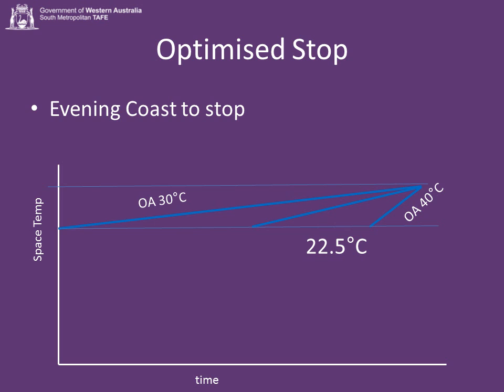What we can do is look at the outside air temperature, look at the inside air temperature, and say, oh look, the building warms up at 10 degrees an hour. If we want it to be just a little bit above set point for 5 o'clock, let's say 32 degrees at 5 o'clock when they leave, it'll be a little bit unpleasant, but then they're leaving anyway, who cares?